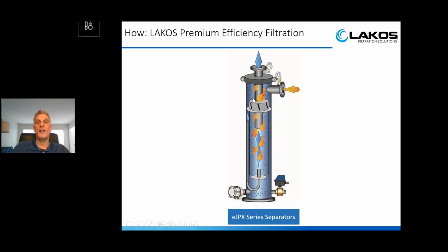So as water enters that top chamber, it's being drawn through those slots, increases that velocity, creates that laminar flow effect, and as it gets in its downward spiral motion, trying to find a vortex, we use a deflector plate right above the collection chamber. So as soon as water hits that deflector plate, it's redirected, and then it picks up the vortex at that point and just follows the vortex through a vortex finder, out the outlet, and downstream.